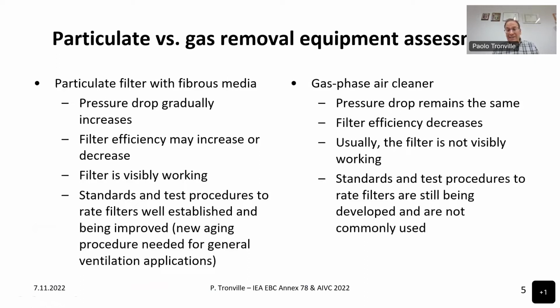In general, we can say that gas phase cleaners are not more difficult, but it's not possible to rate them in a straightforward way, as is the case for particulate filters with fibrous media, especially. As we said before, the pressure drop remains the same, so we cannot use pressure drop as an indicator of service life. The filter efficiency in the case of particle filters may increase or decrease, while in the case of gas phase filters it always decreases.